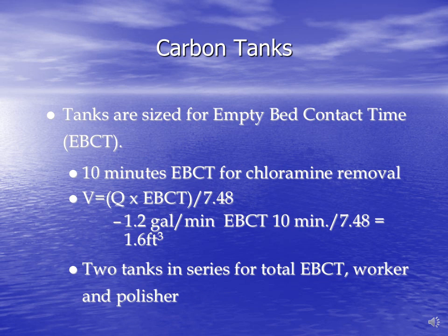The requirements are that tanks are sized for empty bed contact time, and the requirement is that it be a 10-minute empty bed contact time for chlorine removal. What empty bed contact time means is that the water, once it enters the tank, must be in contact with the carbon for 10 minutes before it exits the carbon media, hence the empty bed contact time. The calculation is there for anyone interested in knowing how to calculate.